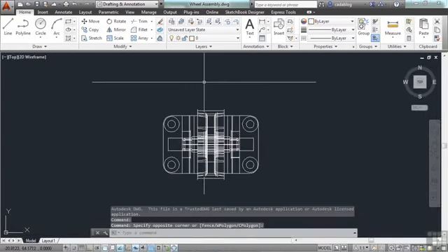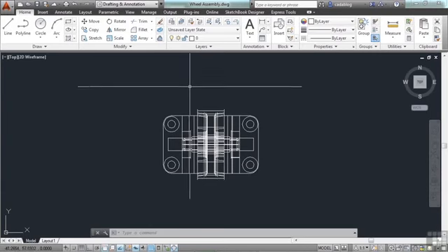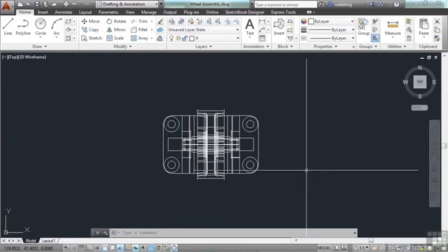Okay, now that our file is open, we want to start a new file. If you're working on a new project or you need a new file for your current project, this is what you'll do. So don't worry, it's really just as easy. Only this time you have a few choices to make. When you turn AutoCAD on, it opens up a brand new blank file based on the default template file. If that's okay with you, then your job is done. You save the file as needed and start drawing.